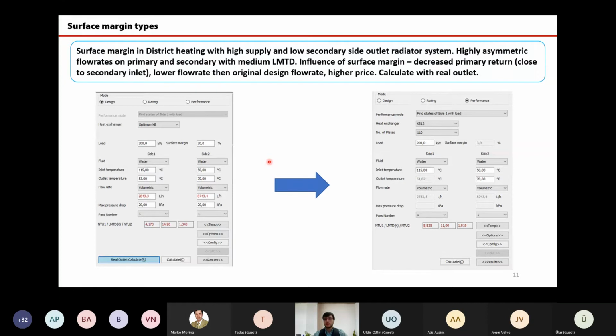But it's nothing like having to keep in mind self-cleaning of the heat exchanger, because heating heat exchangers, be it radiator heating or floor heating, normally work with closed circuits and with heat treated or chemically treated water. That means once the circuits are filled, the water there is sometimes not refreshed for years.